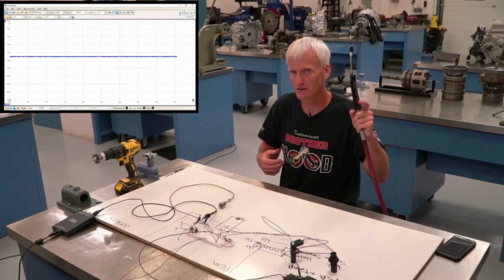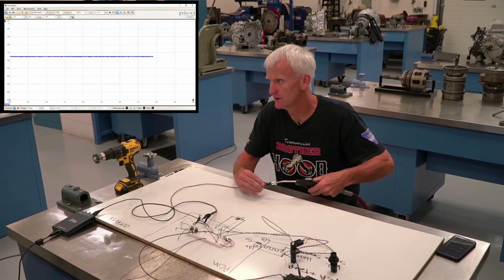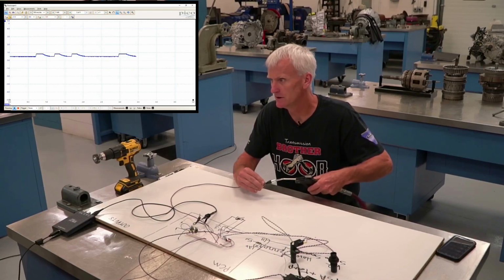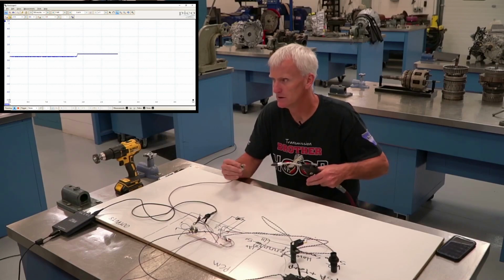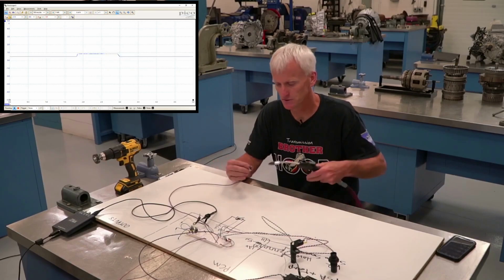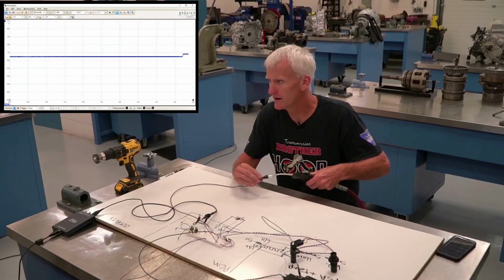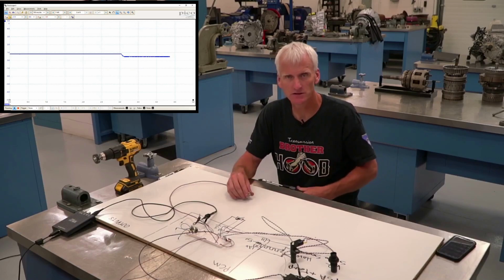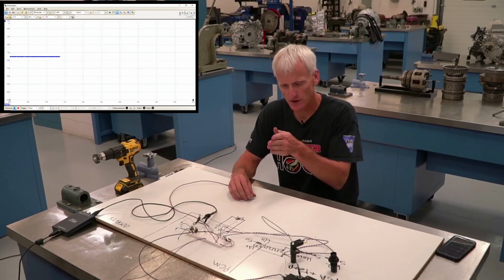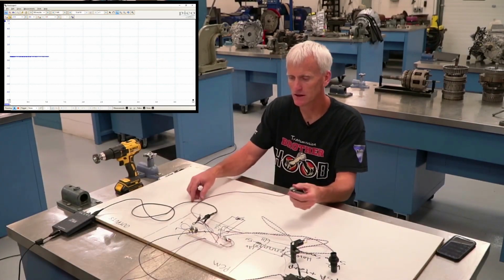So if I took my air pressure instead of hydraulic pressure or ATF pressure, you can see as I gas it, give it a little bit of pressure, it goes up. It goes up to about almost a volt. So whatever voltage it goes to, let's say this has got 60 psi in it or so. I don't know if this was about 0.9 volts. So there's going to be a correlation. There's going to be a table that equates a certain amount of voltage to a certain amount of pressure. So that way the transmission will know exactly what pressure we've got.